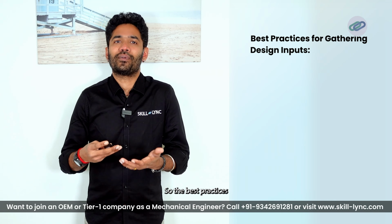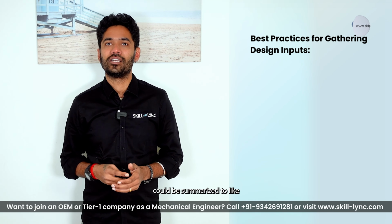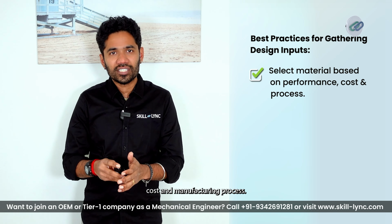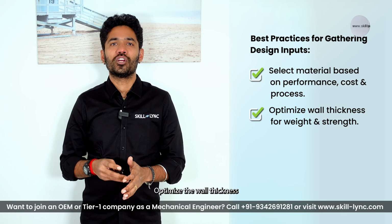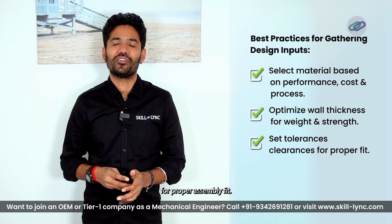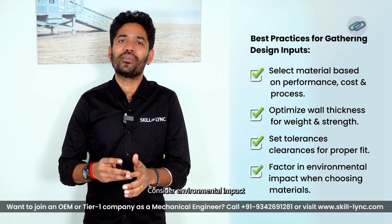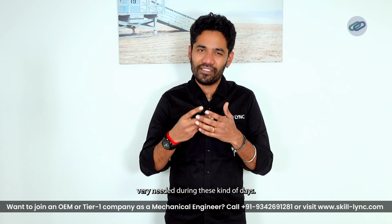So, the best practices for sheet metal and plastic design could be summarized like: choose the material based on performance, cost and manufacturing process. Optimize the wall thickness to balance weight and strength. Ensure proper tolerances and clearances for proper assembly fit. Consider environmental impact when selecting the materials, which is very needed these days.